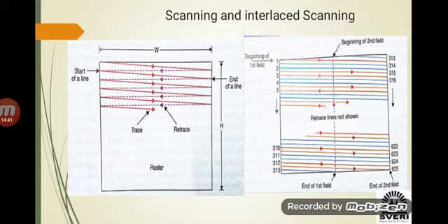Now there are a few limitations in scanning, where we have continuously varying intensities simultaneously. For example, let us consider a chessboard, where there are alternate white and black squares. If we start shooting a chessboard, one image is completely white, another is completely black, another completely white, and the brightness value keeps changing. So there are very huge changes as far as the amplitude of the video signal is concerned.